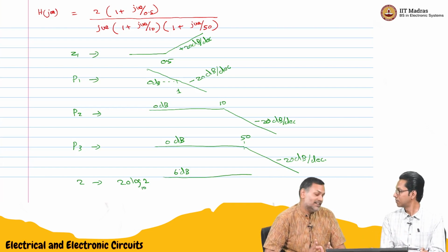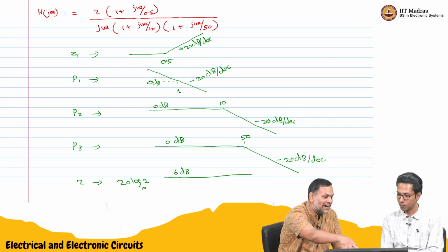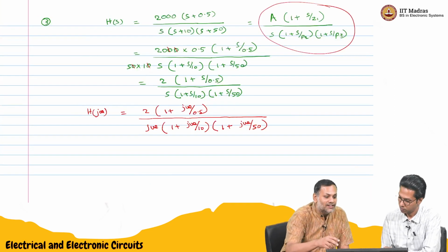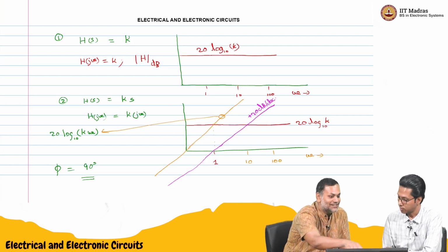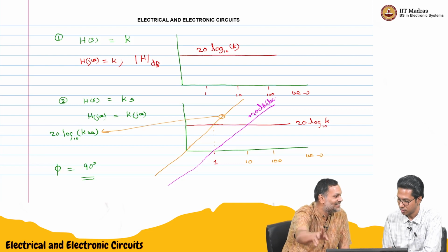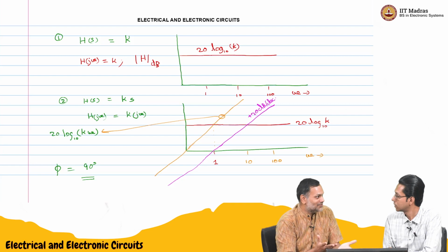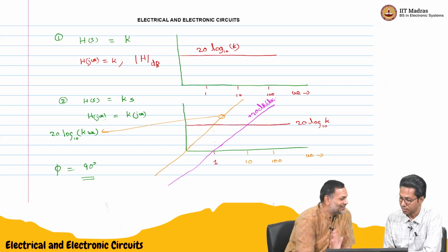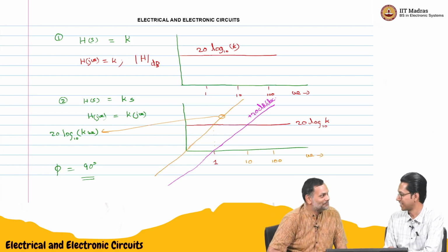The big difference between a pole and just adding these things, you are adding all of these in dB. So if you go to the previous page, the whole curve shifted up, because you are adding them in dB. This is not like a zero where you can just approximate the corner frequency and do it. So they have to shift curves if they are adding constant values. You have to add everywhere, in all ranges, not just approximate saying below this it is small and so on.